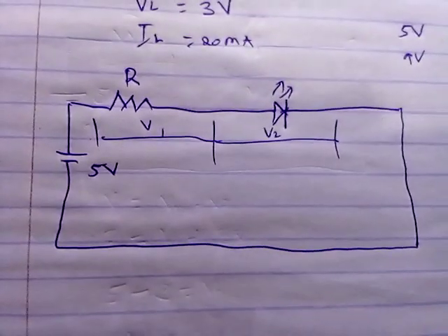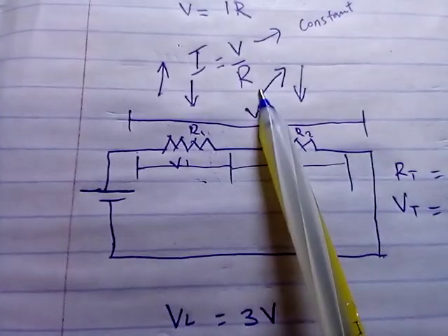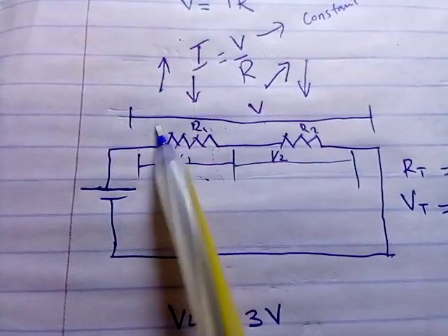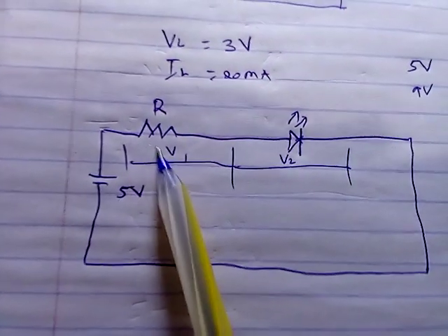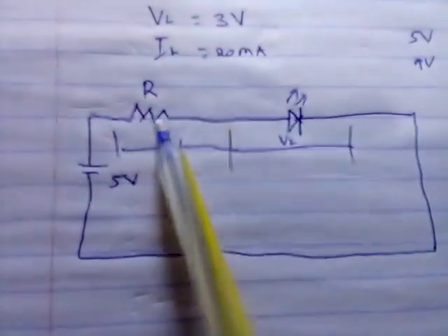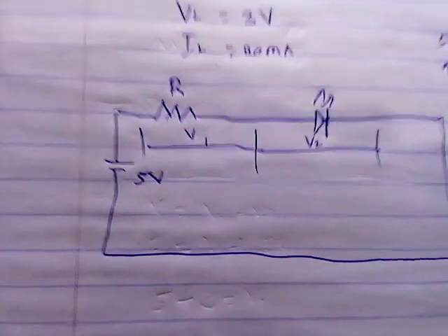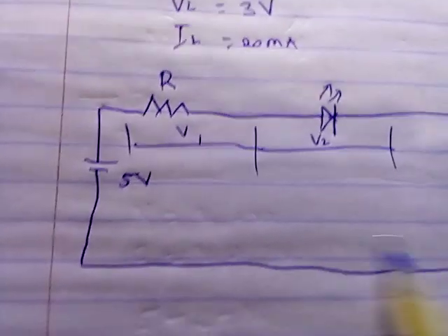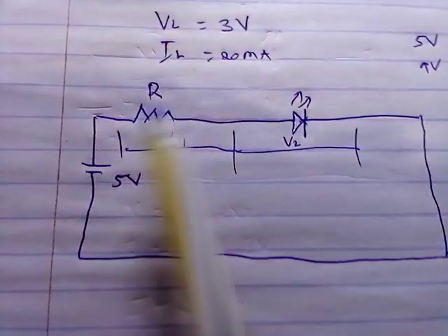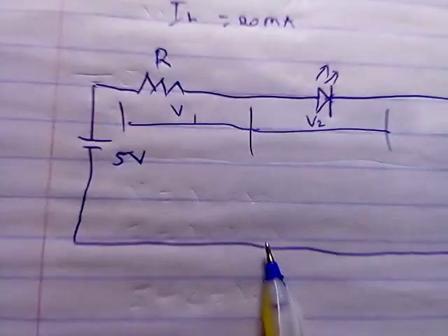From what we have investigated, when the resistance increases, the current reduces, and when the current increases, the resistance reduces. So we can use a resistor to control the flow of current in a circuit. By connecting a resistor in series with the load we want to protect, we can control the current in the circuit. So for the current limiting we are going to investigate, we are going to use a resistor as the current limiting device.